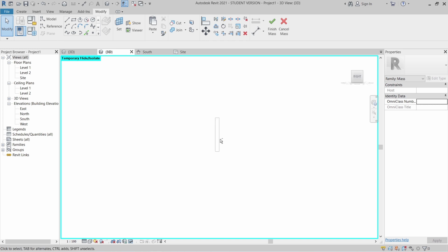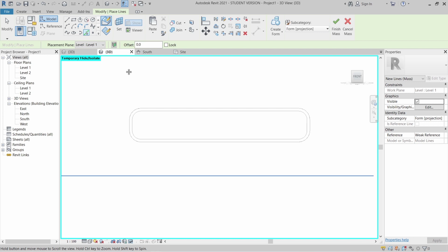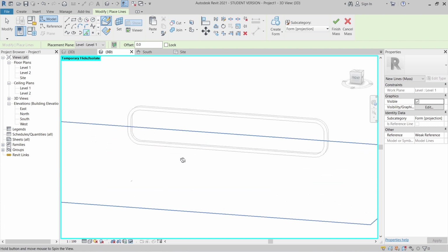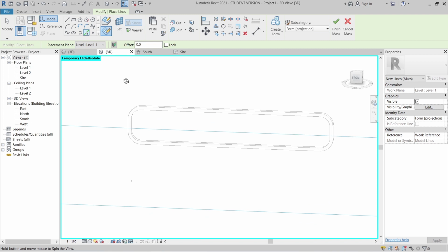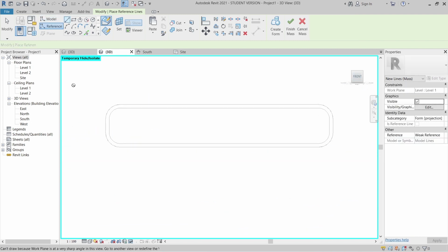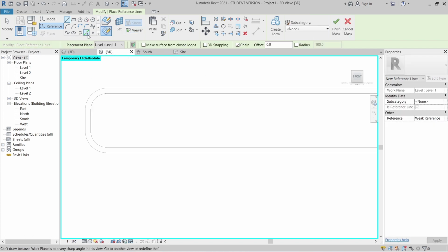Start from right front again. Hit escape a couple of times. Go to our create tab again. Go to pick line. Okay, let me pick first. Is it correct? Okay, not correct. Go to our reference working plane here. Start from plan. Again, we go to use our reference. Turn off 3D. Use pick line.